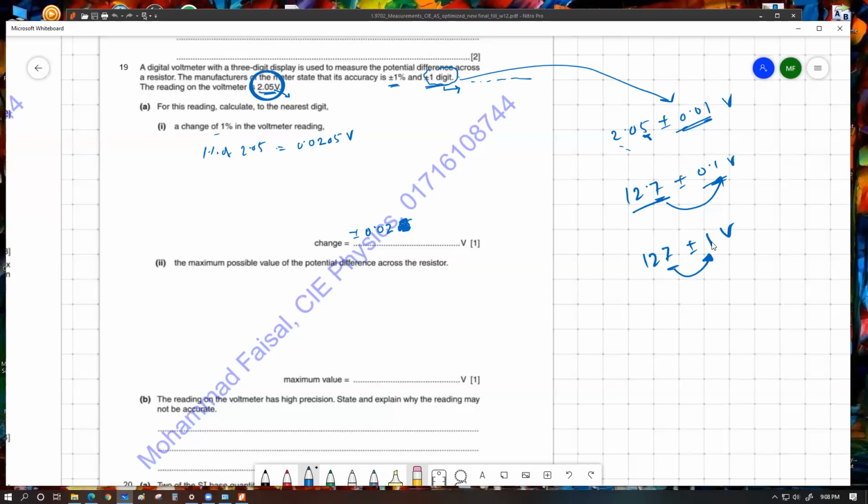Now you might wonder why the device should be able to measure this kind of values. I mean, shouldn't it be able to measure the same number of decimal places afterwards? The answer is a solid no, because whenever we try to measure large readings, we typically lose precision on the decimal sides. Whenever we measure small values, we usually get more precision on the smaller fraction. That's usually how every measurement device works.